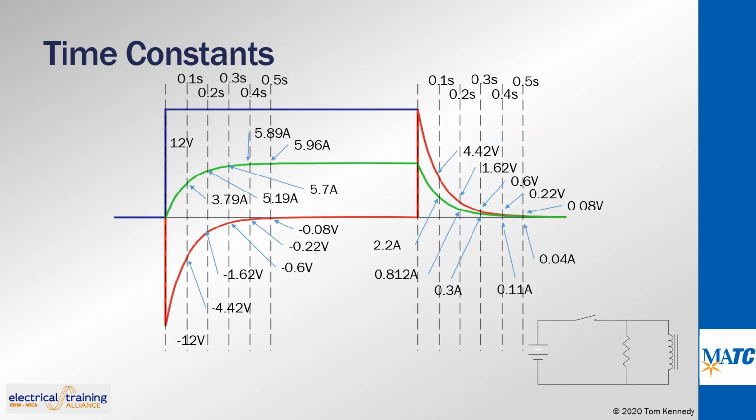The 5 time constant factor can be applied to the circuit as it is de-energized. The current will decay as the counter-electromotive force created in adjacent turns of wire decays. Since the induced voltage and current are in the same direction, they will decay at the same rate. It can be stated that inductors oppose a rise in current because of the counter-electromotive force created by the magnetic field, which is opposite the applied voltage. And inductors will continue to provide current at a decaying value when the DC source is removed.